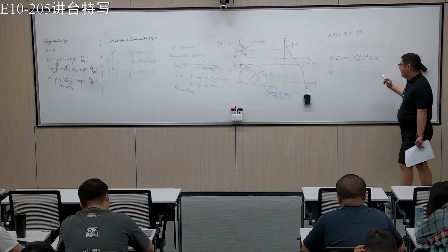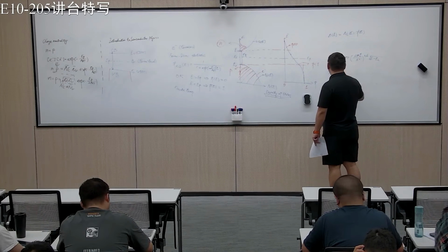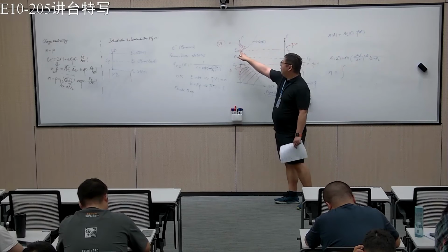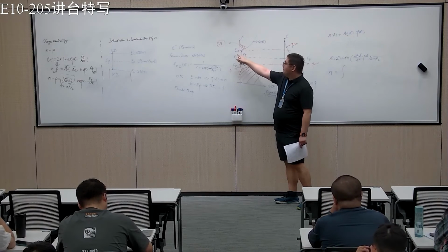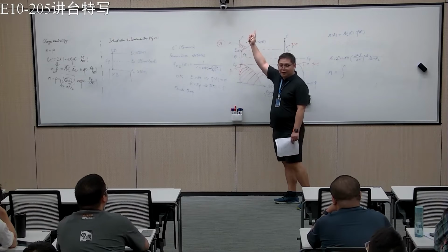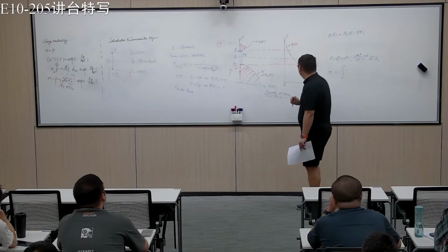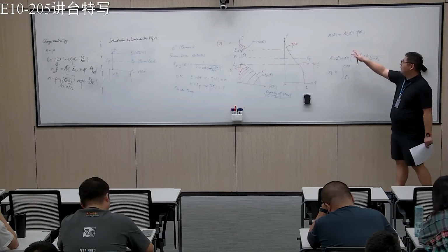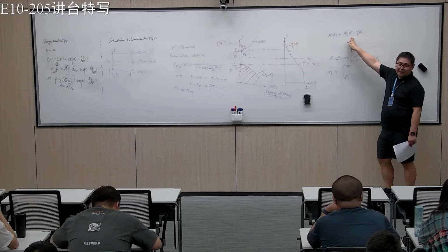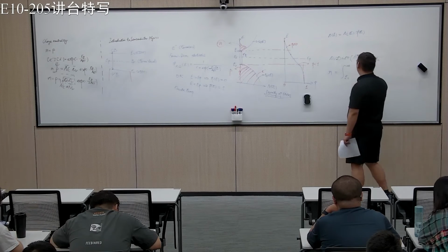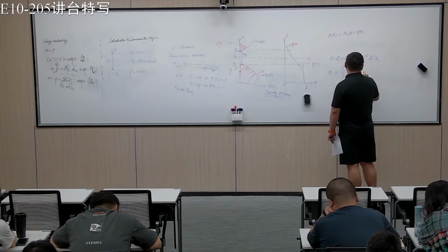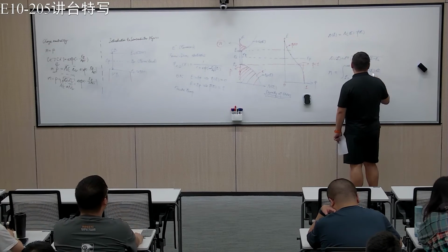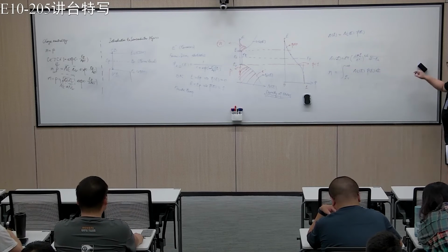Okay. n is now basically an integral, right? You start to have electrons beginning at EC, and if you go above, you have many electrons. So basically from EC to infinity. And we know that at a certain energy, we have this electron density, right? So then we have NC times Fe dE.